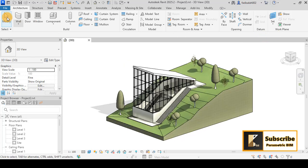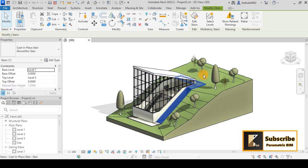For the upper part of Revit, we have tabs, and every tab has its own ribbons, and these ribbons are categorized under some category here. And also we have something called the ribbon context, which is related to any component we select, and it is different from component to component in the Modify tab.